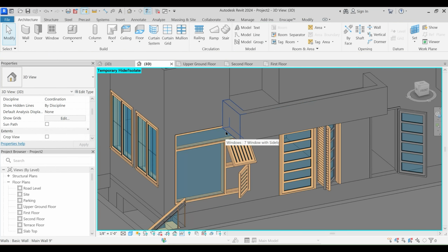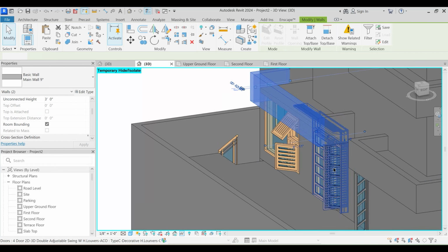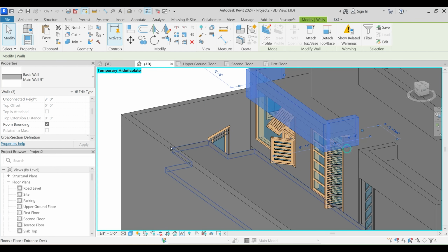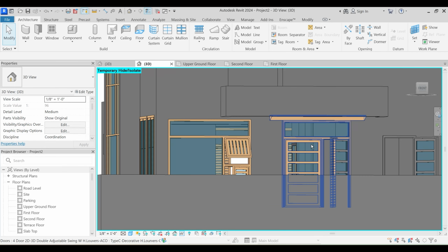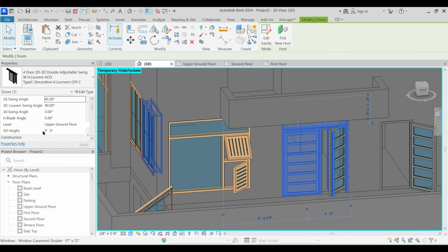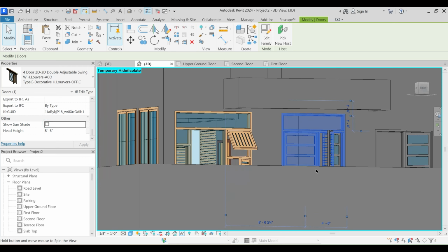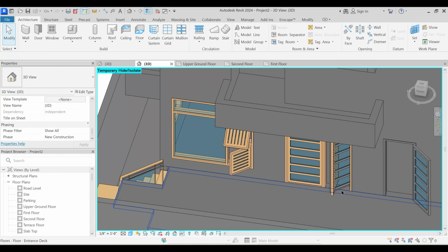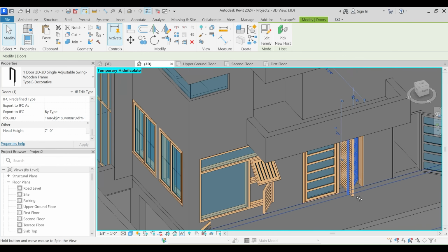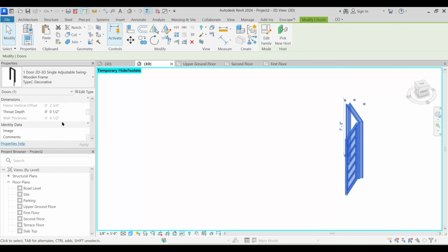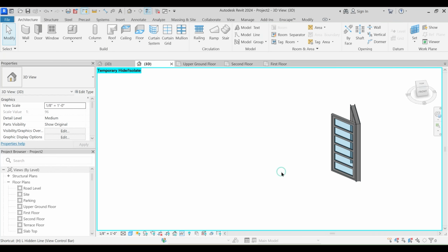So what I'll do is that right now, just for the design purpose, I would say that the base offset should be minus 1 foot only. Fine, and no issues. And from this door, I will get rid of the shade as well. And fine. Okay. And here there are two doors, I guess. Yeah, that is the door of insides, which is having this swing, and having an instance parameter which I can flip. So just change this to swing angle 45, and that won't disturb us anymore.